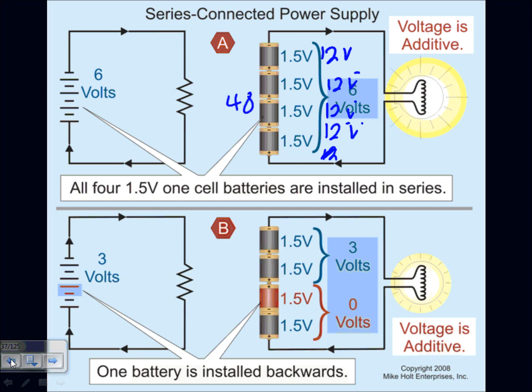48. Now, imagine multiplying this by 10. That will give you 480 volts, right? Imagine 40 of these, right? 40 of them. I have 1, 2, 3, 4 times 10, 40. 40 of these 12 volt batteries tied together in series. They get you 480 volt. That's how they do it in data centers.